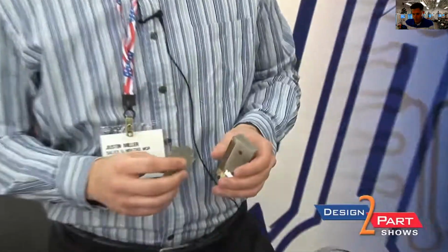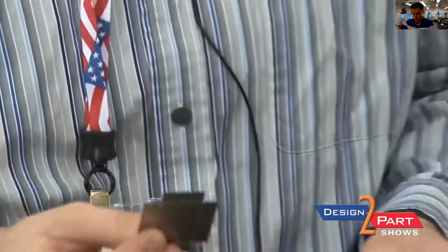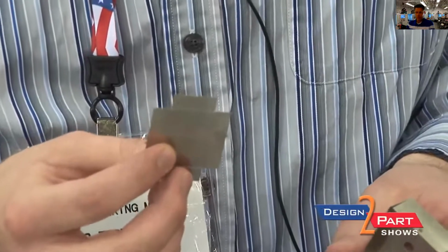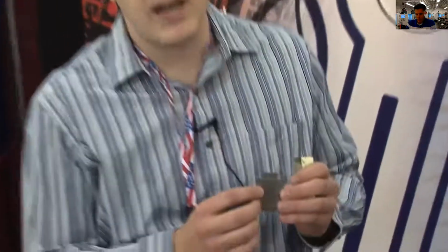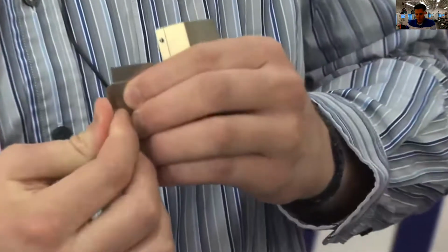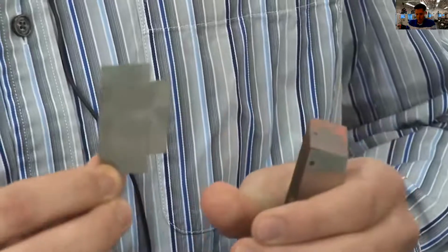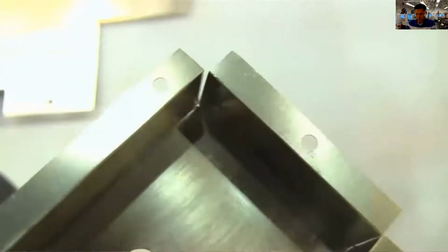These things right here are shields. This material is actually called nickel silver. It's a copper nickel zinc alloy. The advantage of it over, say, copper is when you use it on a circuit board, you can solder the base material without needing tin plating. The other thing we'll do is put these half etch lines in there, so you can fold the sides up and make a box. So instead of needing hard tooling, this half etch line will help you get that straight edge so you can get a good 90-degree angle on it.